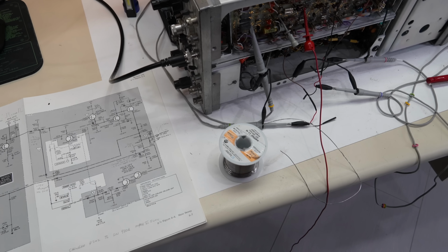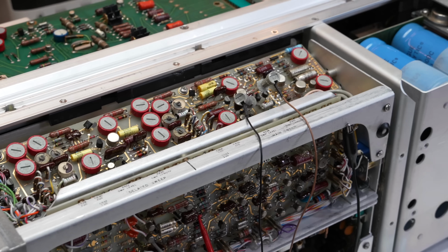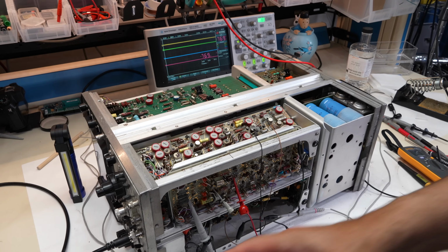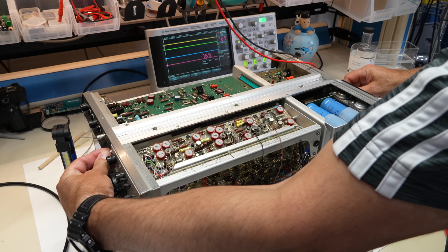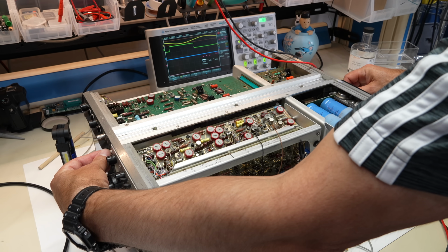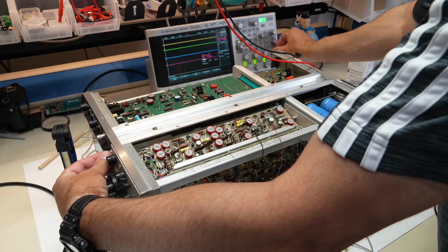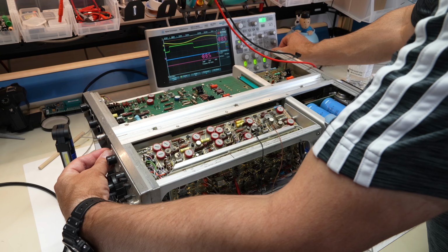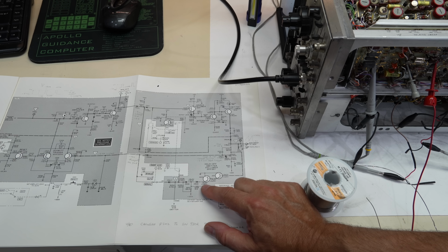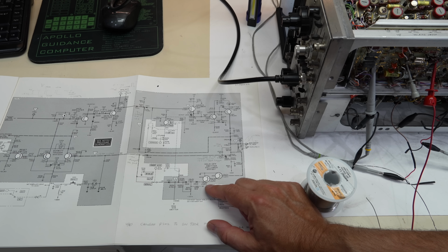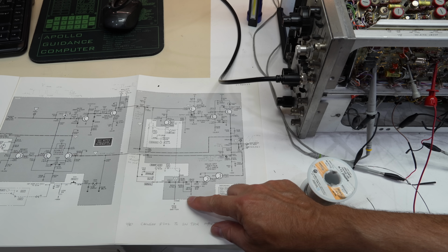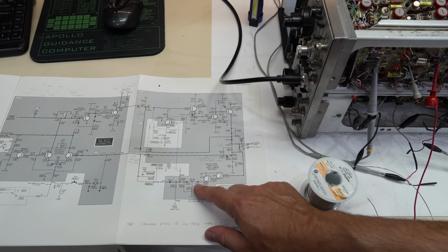All right. And we are right back in the circuit where this was monkeyed with. So now the red and the blue should follow each other. Let's do it. All right, well, we have a fault. The red is not following the blue at all. It's at minus 88 volts. What? So I'm here, I should start at minus 25 volts and go up to minus 2.6 volts as it ramps up. And I am stuck at this super low voltage, which is very, very low. It probably blew everything afterwards.